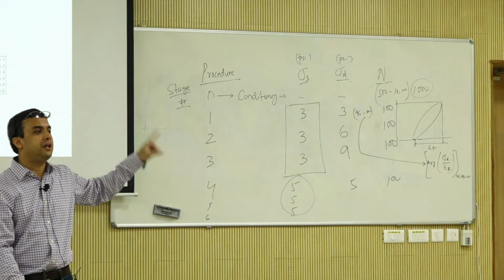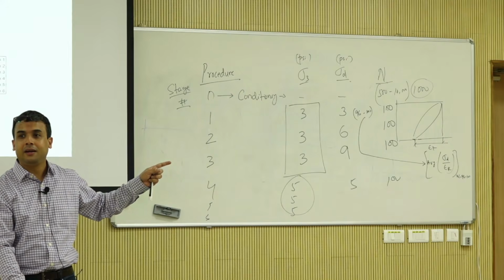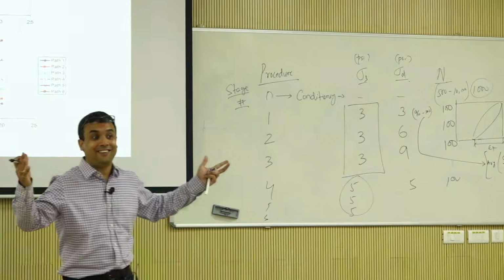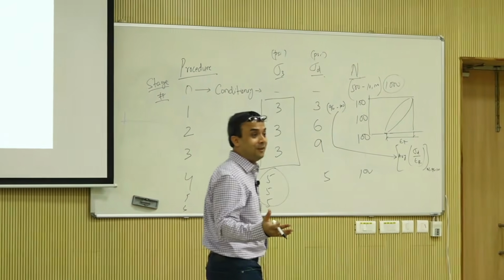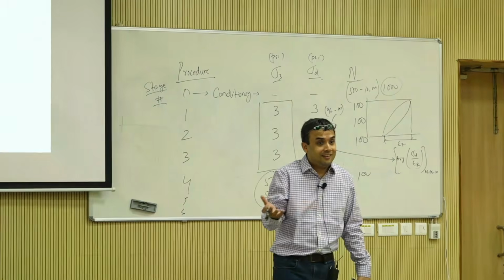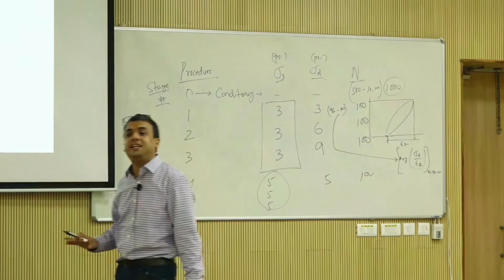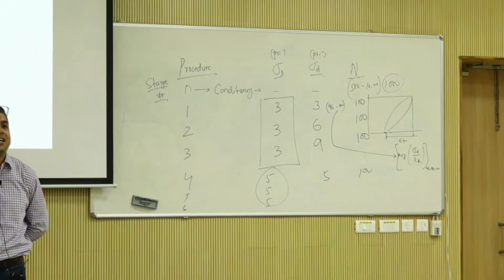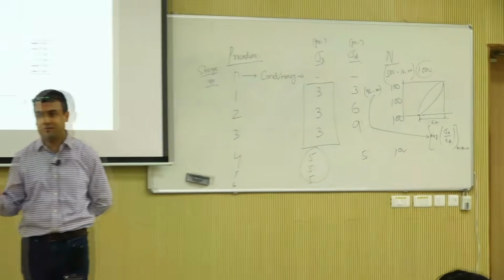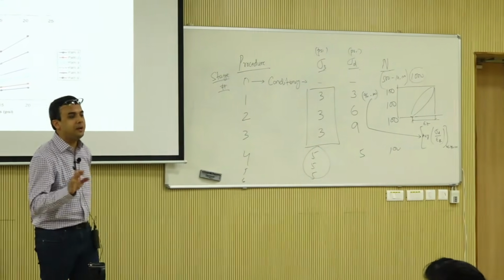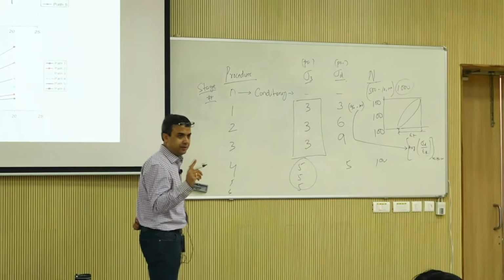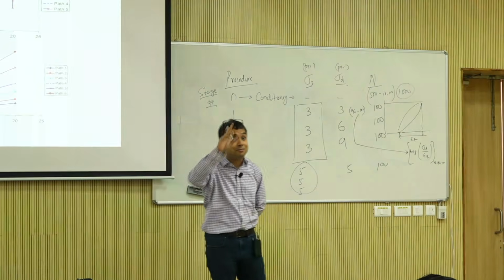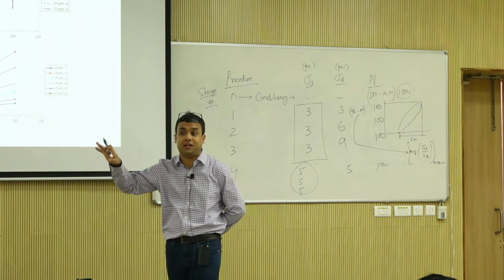So if I ask you what is the resilient modulus of this material, what do you say? It depends. Tell me the stress state. What stress state is it? E is equal to 30 ksi or 30,000 psi, that's an elastic representation. That is not resilient modulus. Resilient modulus is not one value. A material cannot have a single resilient modulus. You can take a representative modulus. That's a different thing. We can talk about that tomorrow.